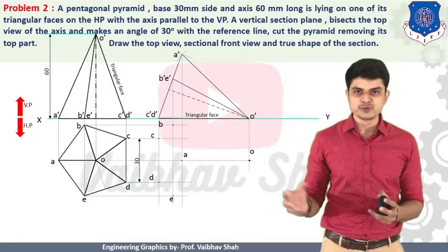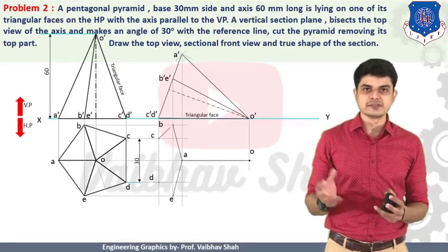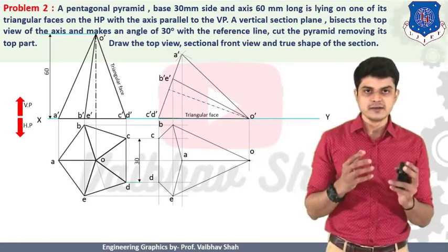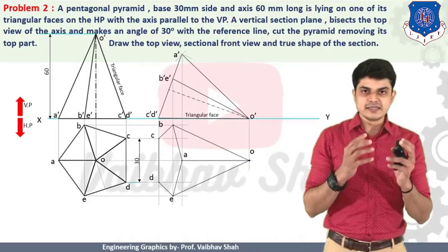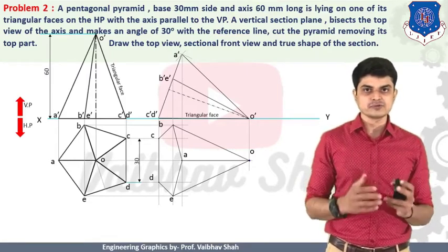After getting this point, you should connect the outer boundary surfaces, and you should join each and every point. Let us join each and every point in order to complete the pentagon. But here, let us try to visualize if any element is missing or hidden by taking the top view. So let us try to observe.